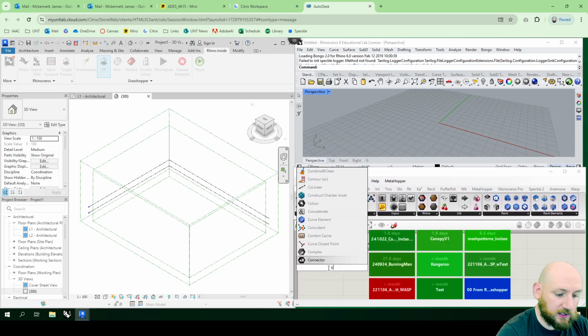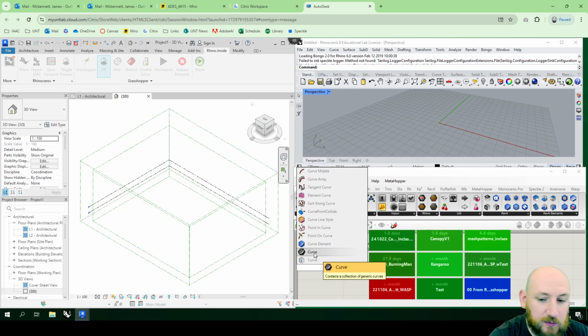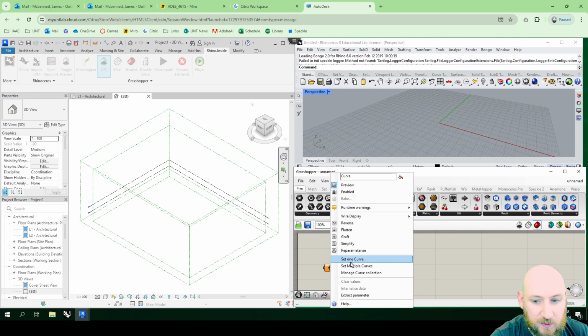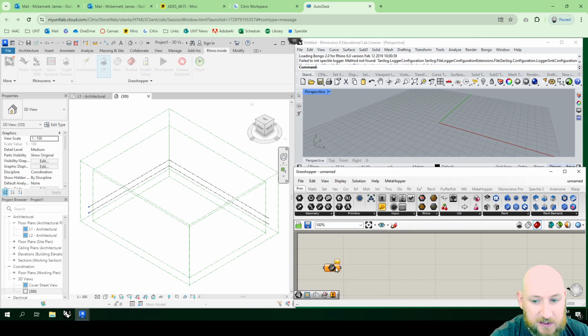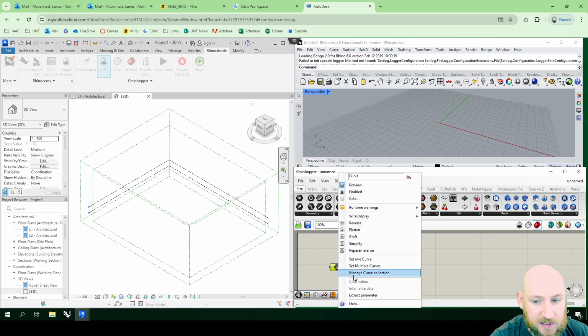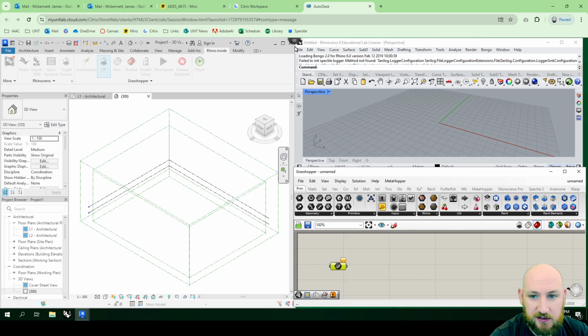Okay, I'm going to do the example I did in class again, just as a pre-example. So I'm going to do a Curve to link a curve from Rhino, and it has to be this curve. This curve here is to get a curve from Revit. If I was trying to draw a curve in Revit and bring it into Grasshopper, I could use this component here with the gray background. And I had the one with the black background, which is the Rhino native one. For some people, when they clicked set one curve, that was why, because they were in the wrong curve component. When they would set one curve, it was trying to find something in Revit, not trying to find something in Rhino. It's important to set which direction you're going.